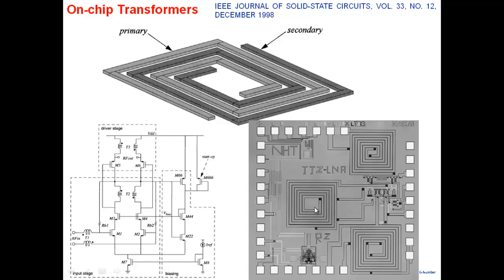So the MOS technology is best suited for what? Best suited for making an NMOS and a PMOS. That's it. Resistors are not very good. Capacitors only of small value. Inductors also of not a very good quality. Literally, quality factor is poor. You can make transformers. You can get some coupling coefficients. But